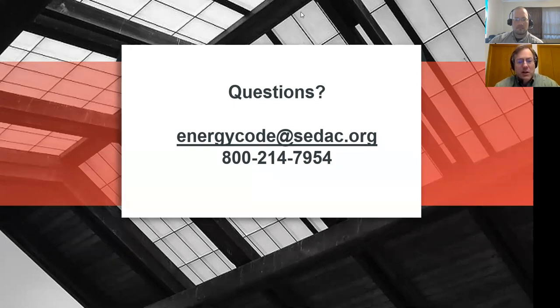The second question was which systems require functional testing. This was a little bit more difficult because all of these require functional testing. You have to test your occupant sensing controls, your daylight harvesting controls, your time switch controls, enhanced digital lighting controls if present, and your luminaire level lighting controls. So you do have to functionally test all of these. But people picked up on this pretty well.